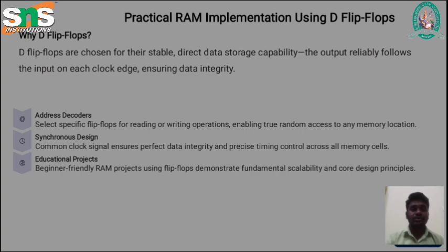First one, address decoders. They select specific flip-flops for reading or writing operations, enabling true random access to any memory location. Then synchronous design: common clock signals ensure perfect data integrity and precise timing control across all memory cells.